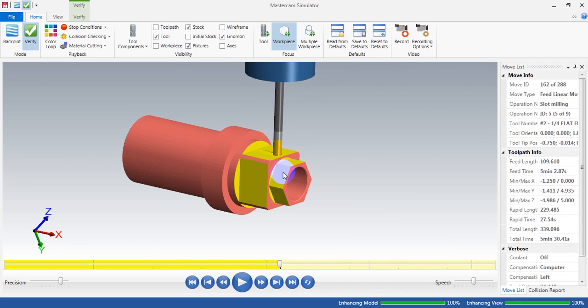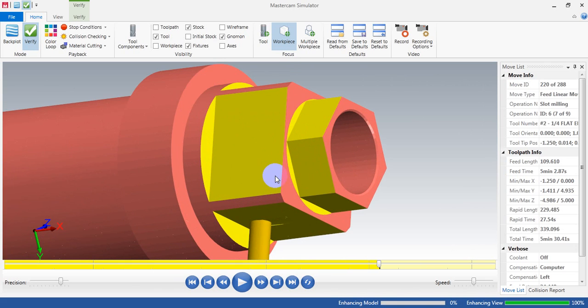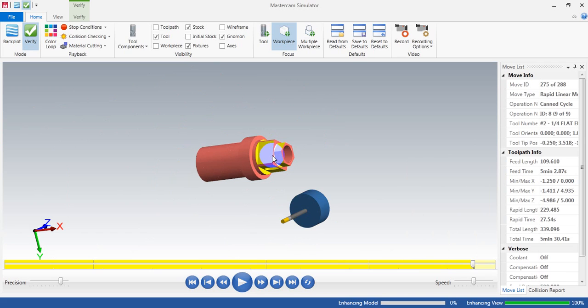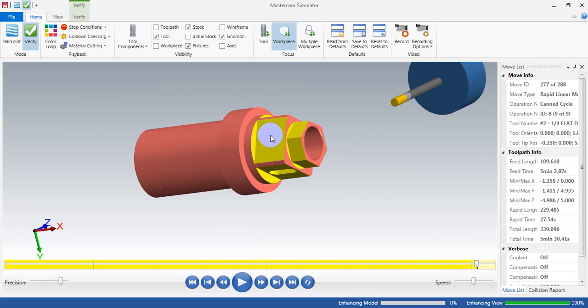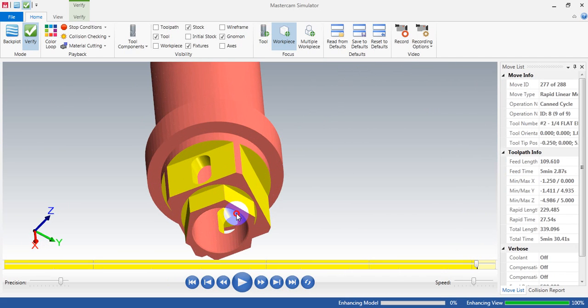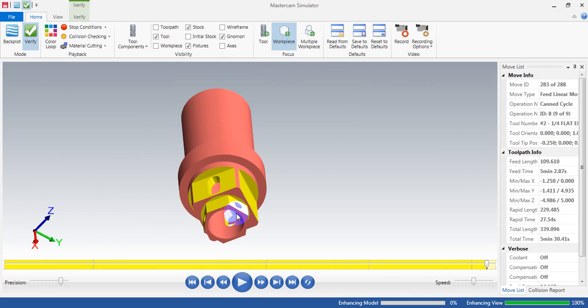Okay, and this is the slot milling at 0 degree, and after that we rotate the tool plane 180 degrees to machine the slot on the bottom face. Okay, you can see that it's very simple to create an indexing job by using the toolpath transform. And now for the drilling operation: the first hole with the A60 tool plane, the second hole, and the third hole.